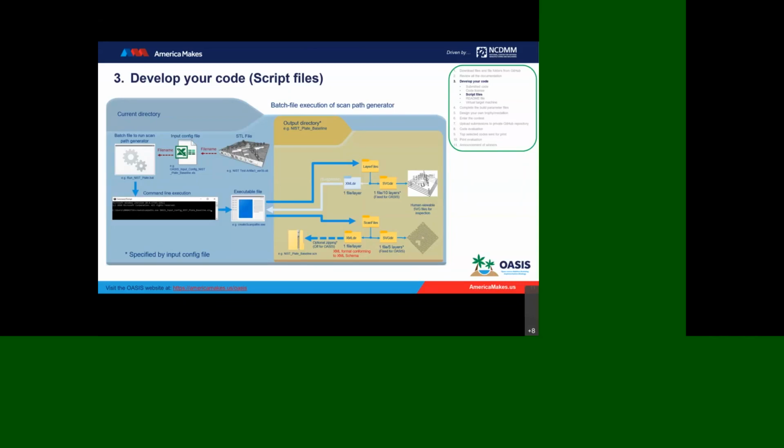All right, optional output for the layer files, or I guess suggested output, would be in the form of XML files. So when you download the baseline code from GitHub, this is how the code is structured: it generates XML files that describe the outline of each layer slice. Those get returned to the executable file, and then the executable produces scan files. So 2 types of output for the scan file. One is, again, support vector graphics for visual inspection. This time we're setting it at 1 file for every 5 layers.